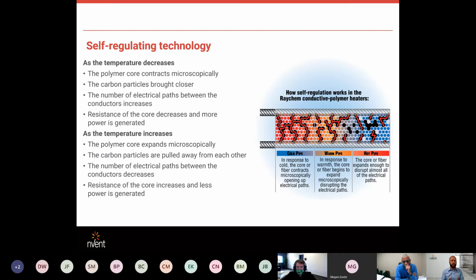And it is. The problem is that if it's left on indefinitely, it will slowly trickle heat into that pipe. With safety showers, there's hardly any flow, so that water is sitting there, stagnant, slowly absorbing that energy. It is not uncommon, if you let electrical heat tracing, a self-regulating cable, cook in that line, for example, I've seen a 1-inch diameter copper pipe and the water get up to well above 120 degrees.